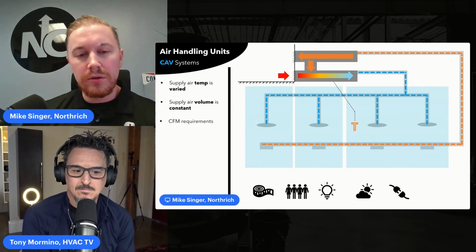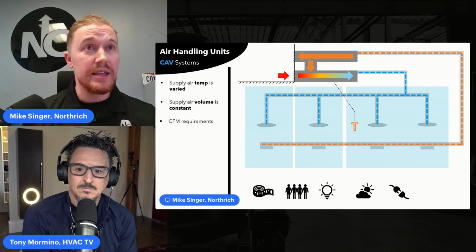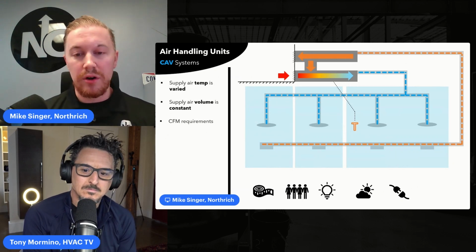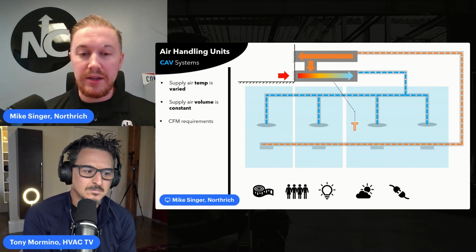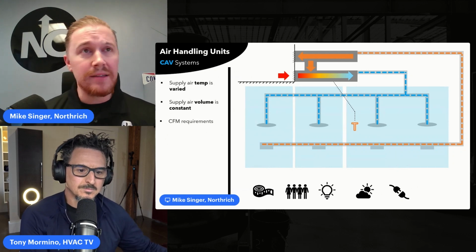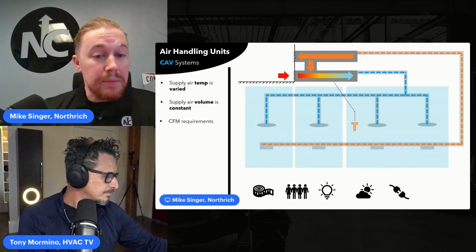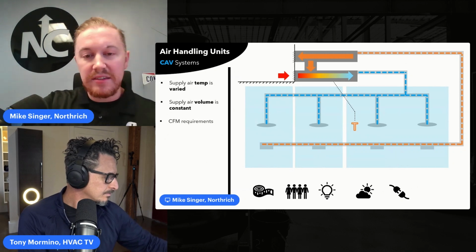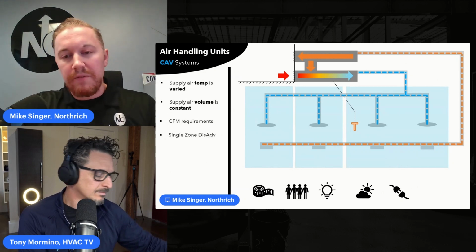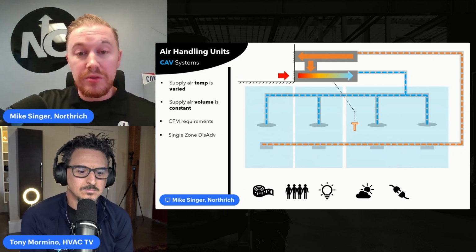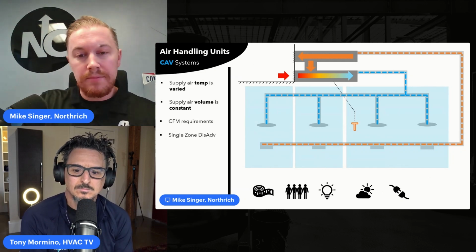How do they do a load calc? Well, the engineer will take into account the heat generation that they see in these spaces during summertime operations. So that might include solar gains, plug loads, lighting loads, and people. And they'll take into account the size of the room and the envelope of the building. What are the R factors and losses we're going to see through the exterior walls and so on.